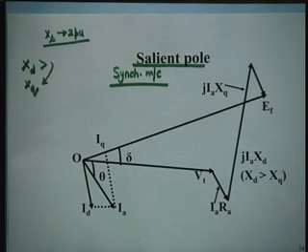The trend is that SCR ratios are coming down, because SCR is the inverse of XS, short circuit ratio, SCR, not silicon controlled rectifier. SCR has so many other meanings also, right. So, short circuit ratio is inversely proportional to XS.